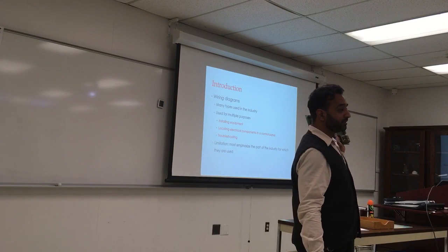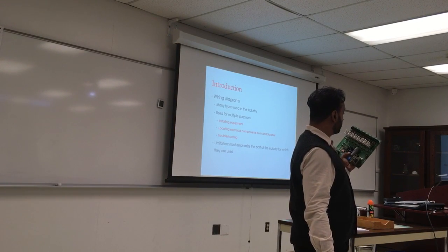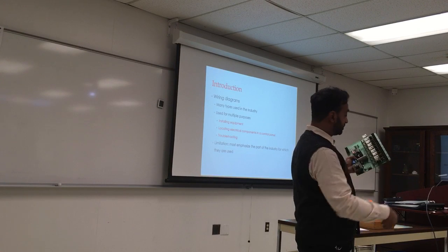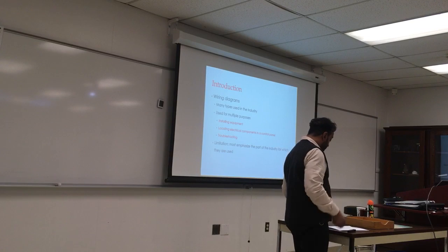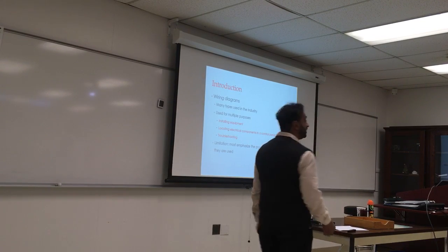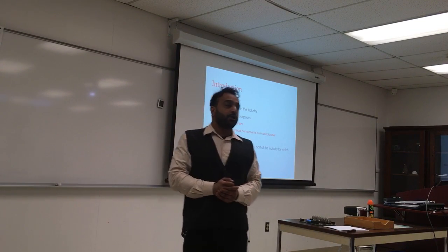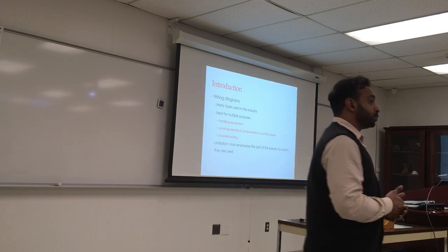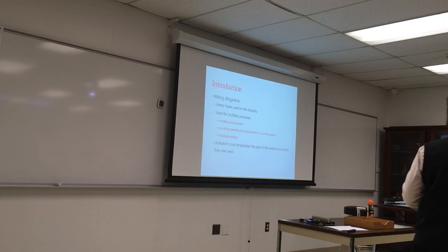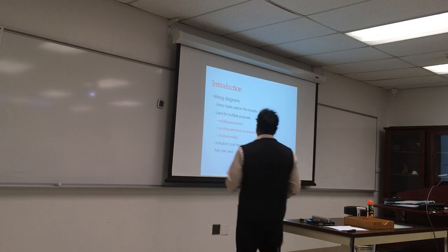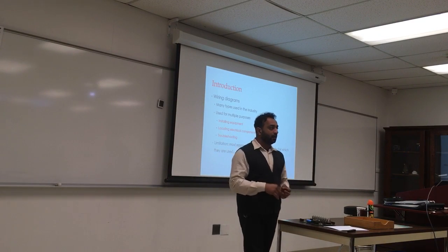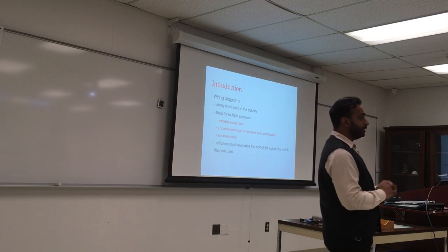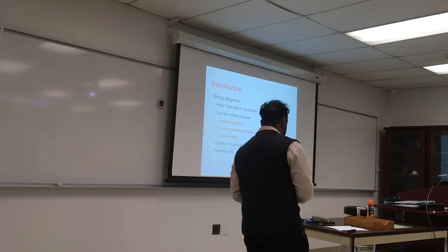What is that exactly for? This is a switching relay for different zones, multi-zones. These are the relays, actual relays, switches. So we need to know the installation diagram and make sure what kind of wire goes where. Usually they are numbered and sometimes they are colored. Where are the electric components in the control panel? What power source goes in which terminal, and how to troubleshoot.